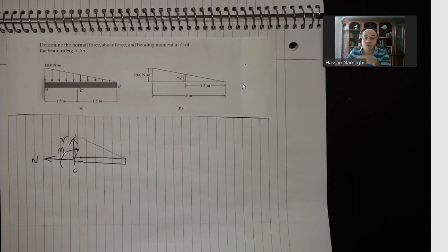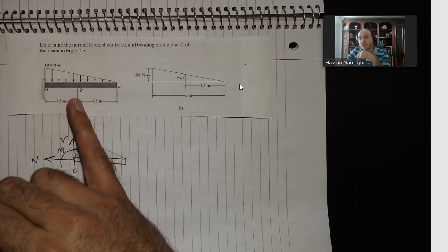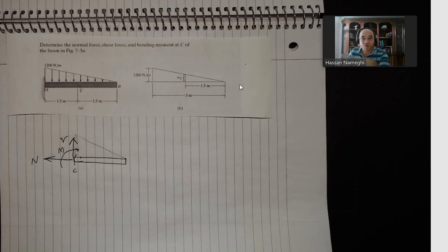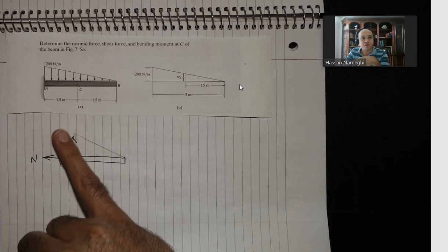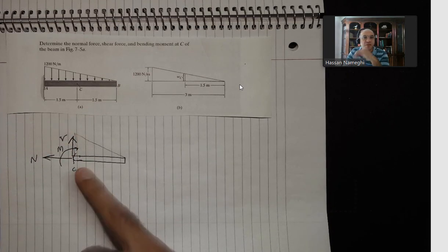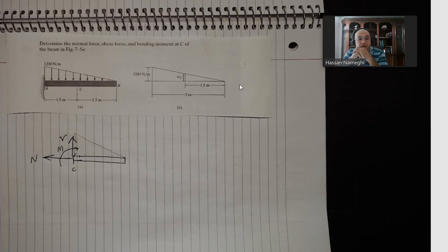Now, internal force. We want to find at point C what the normal force, shearing force, and bending moment are. What I did, I cut the structure at point C, and wherever you cut it, you have to stitch it. The way that we stitch it is with N, V, and M: normal force, shearing force, and bending moment. Now, what I have left in this case, if you look at the structure, already has a triangular load going up there.